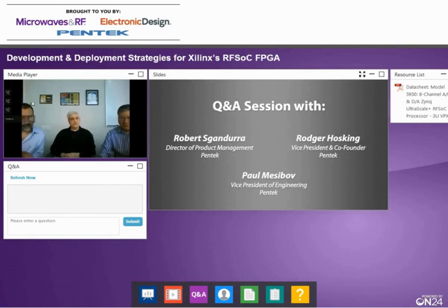Our next question is, how does the 3U VPX board deliver 100 GbE signals? Well, the way we have that connected is by using one of the OpenVPX standards, which is called VITA 66.4, which gives you optical lanes that come out through optical to electrical transceivers on our 5950 carrier board, so that we are engaging with blind-mate optical connectors.